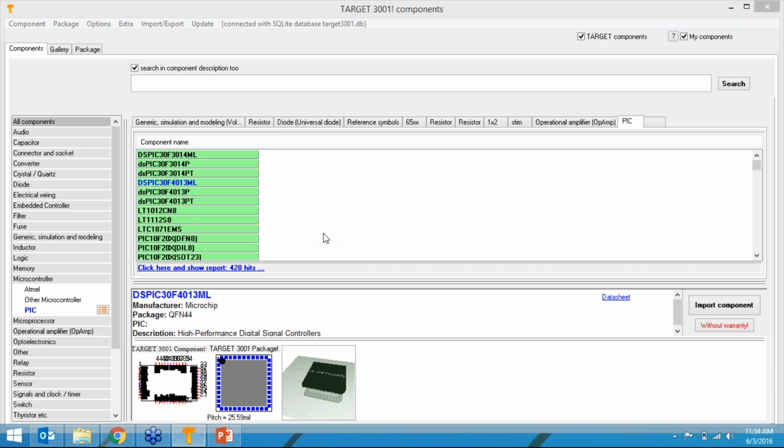There is one question of interfacing between CMOS circuit with DSP. So interfacing is not available, sir. You can design the circuit and analyze it and create the PCBs. Can we design simulation profile of any sensors? Simulation profile can be created, sir. We have component creation wizard. In that, if you have the SPICE coding, you can create those components, and by writing their simulation profiles, you can create it.